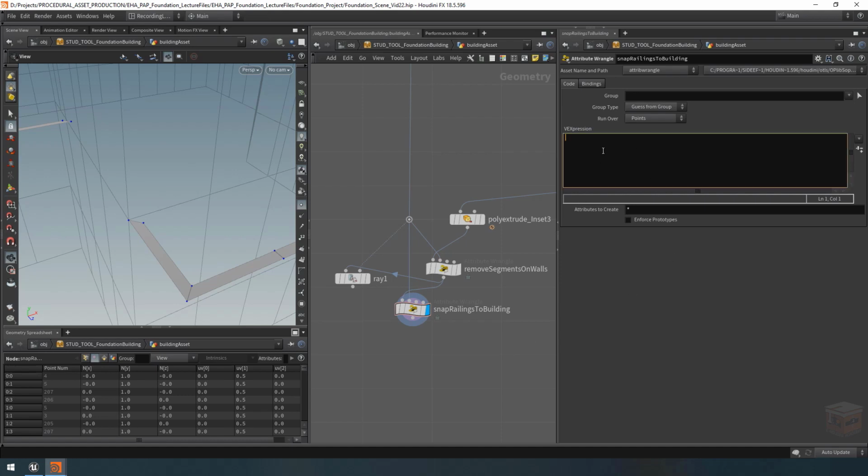So over here, let's write an xyzdist expression. We need to grab the distance value, so let's create a float called dist. Inside the xyzdist, let's sample from input 1 from our current point position. Because we also need to retrieve the location that the point hit in order to snap to it, let's grab the primitive and the UVW coordinate as well. To make that work, we need to create the integer local variable for the primitive and the vector local variable for UVW. So this will read that and write it out. I'm not going to limit the maximum distance; I don't want to worry about that.